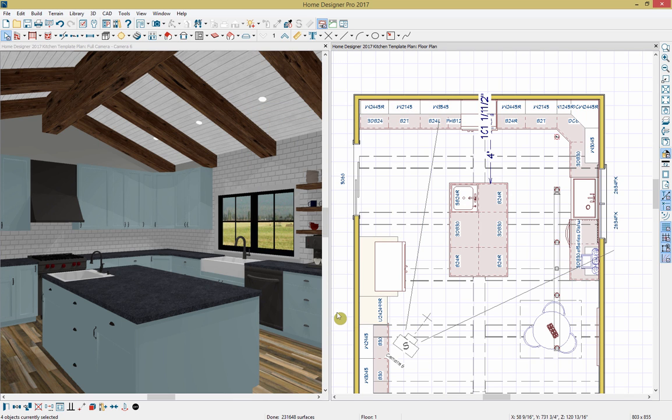And you can see that the lighting has adjusted for our plan. So I'm going to hold Control and grab that last light and we're going to copy these lights and reflect them within our plan. So we'll just get in here and reflect them over. This is a quick way of displaying our lighting.